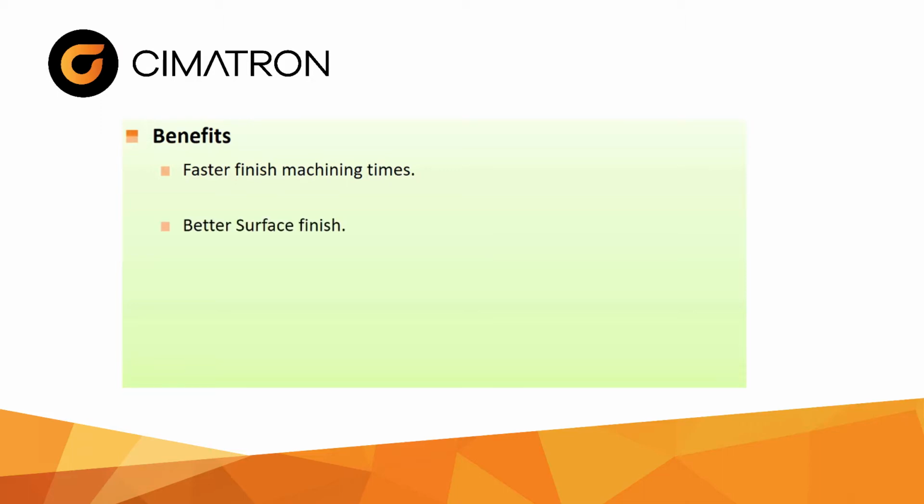Typically we can also attain better surface finishes when the right speeds, feeds, and chip load are applied. And we can also see longer tool life because we're cutting with more engagement of the tool.